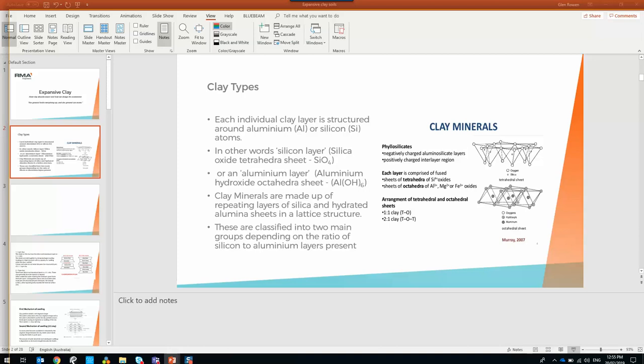So that's it. It's really just understanding the nature of how it absorbs moisture and its ridiculous amount that it can absorb. And even things like, I don't like cut-off drains and ag pipes around things to protect pavements because it can introduce water. So it's really just understanding how it works and being a bit wary of it. But there are certainly ways to deal with it. The best way being go nowhere near it and have everything up out of the ground.